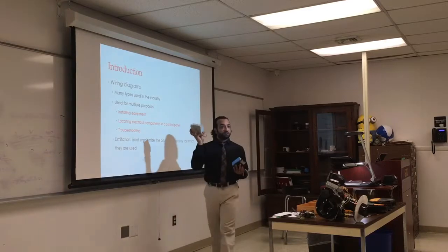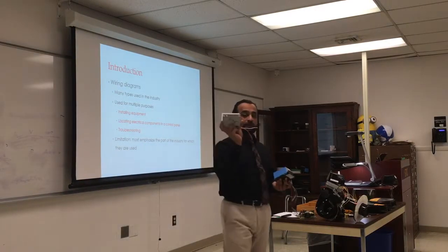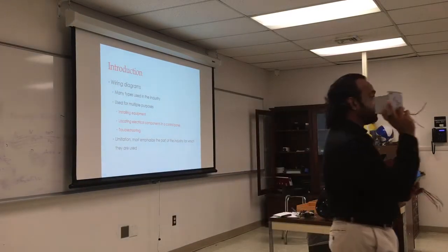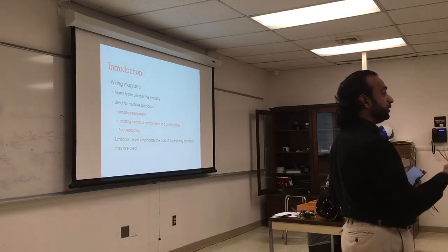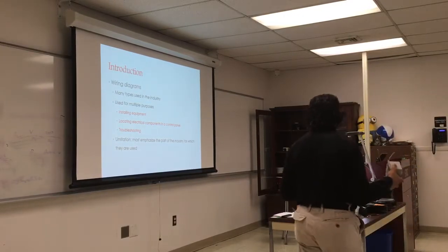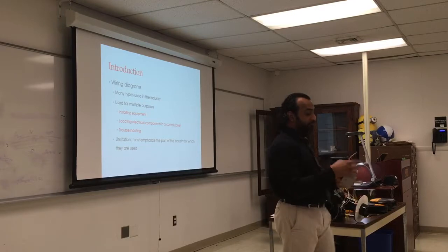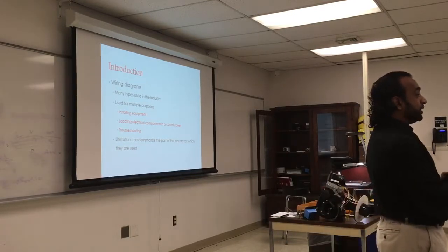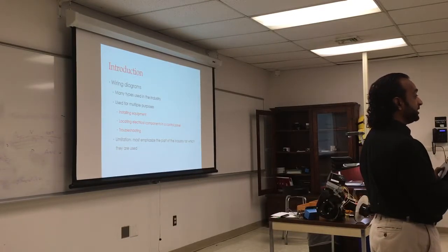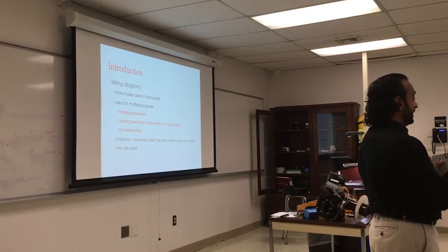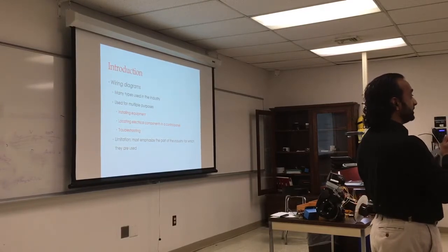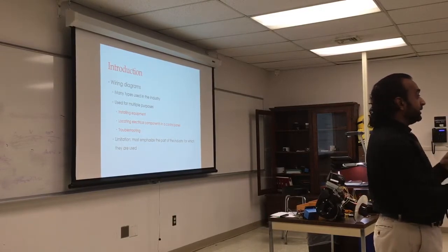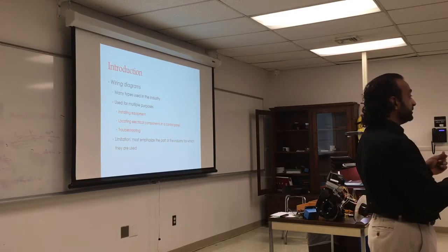primary control. This is the first primary control. It has only 3 wires. That's it. That means less controls and only one button. So this orange wire, everything goes to the orange wire, so everything turns on at the same time: ignition, motor, and valve. It's a wasteful way to connect all these components together.